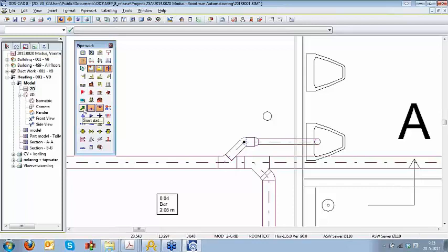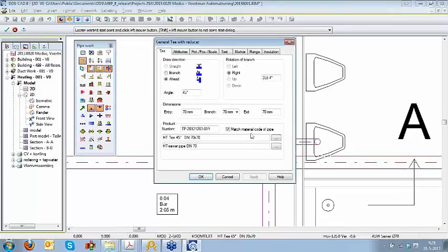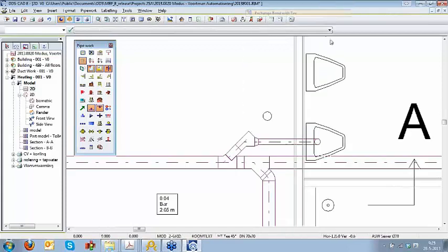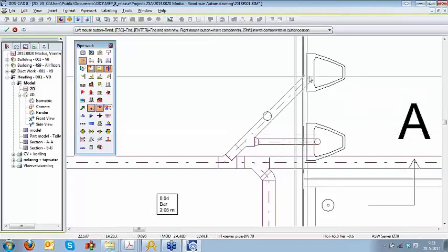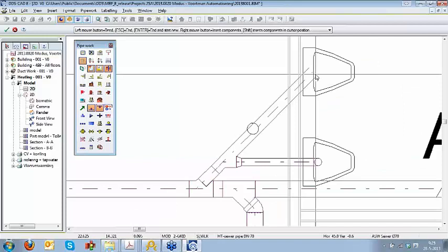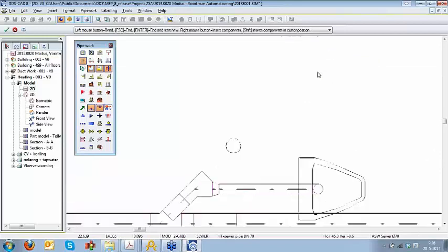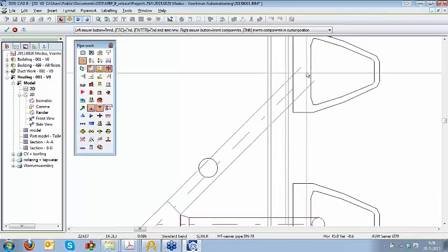And for that I just have to start with Smart Start. DDS knows that this bend can be replaced by a T, and we can start from the T and make the connection. And as you can see right now, the urinal itself also has a connection point available to our sewer system. So we can see we are starting after the T with DN70, but the connection to the urinal itself is set to a DN50. So what we can do, we can make the connection.